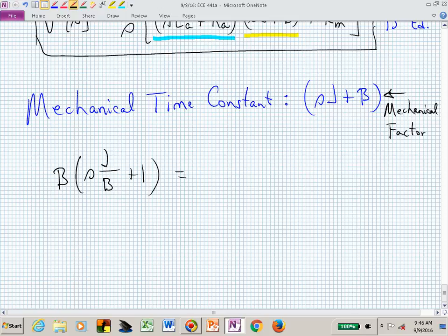If you remember your Bode plots, we had to put factors into time constant form. And that meant we needed to make our constant always 1. Now we've made our constant term 1, and what was scaling S was our time constant, and that's J over B.